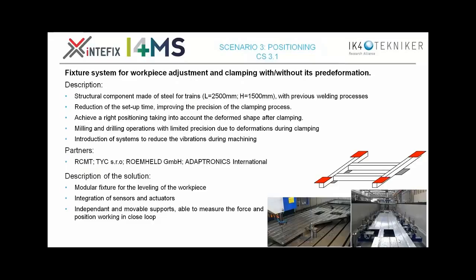That is, for instance, I want to know how this workpiece is located in the machine, and I know where the component should be. So I try to move the clamps and the position of the different clamping elements in order to move the relevant geometrical features of the component to the right position.